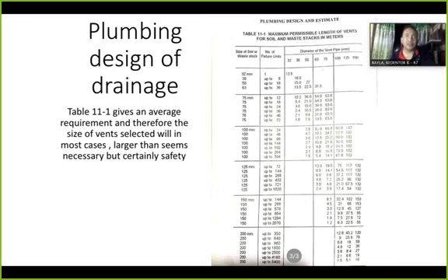Sometimes there was a construction who forgot to provide ventilation. So the problem now, you will see on the line that there are modifications, alterations for the ventilation. Of course, on the long line, you can cut it out and connect the ventilation, providing for the standard distances from the fixture, from the P-trap, and to the provision of the ventilation pipe.